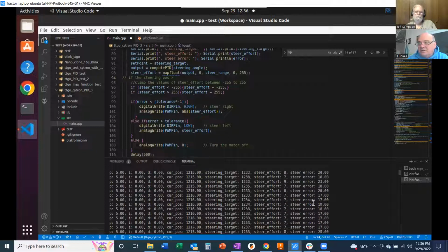It's to limit vacillating the motor when the target and the actual are pretty close. It lets the target and the actual be close, not exact. Okay, I would say when you're all done, you want to remove that. You shouldn't have to put in a trick to calm it down.